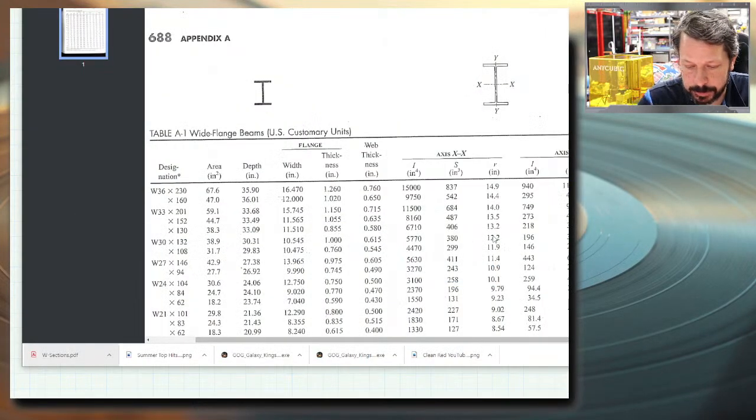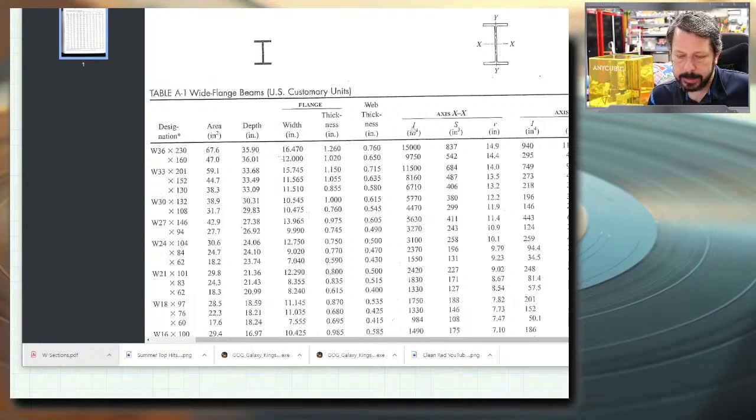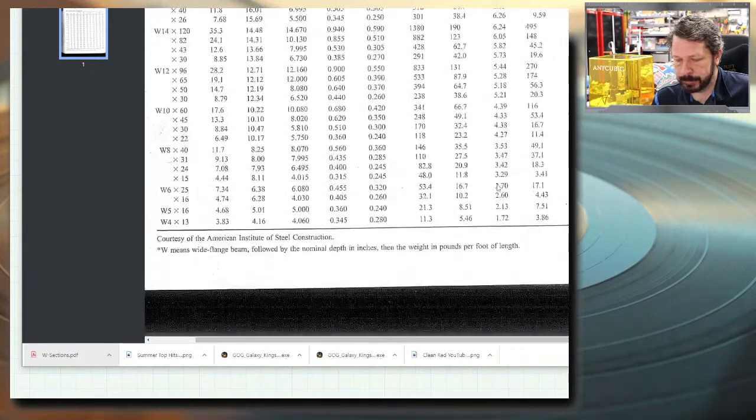So what those numbers are, and we'll use two of these. We won't really use R, but I, you have what's called the moment of inertia. This talks about how stiff the beam is. S, we have section modulus. We'll use that when we're trying to pick out a beam from a list of possible candidate beams. Then you have R, radius of gyration. We won't really use that.